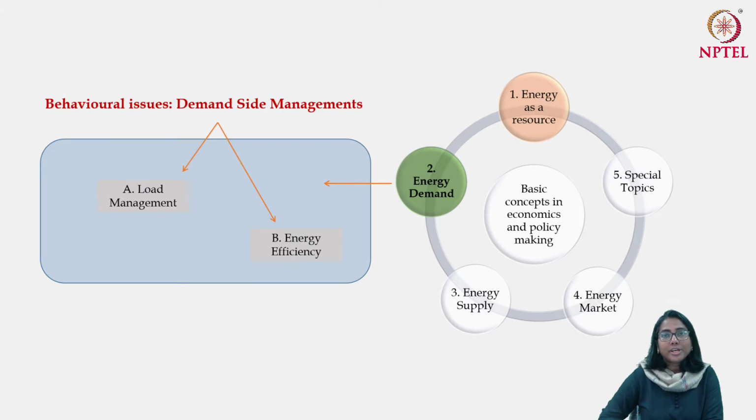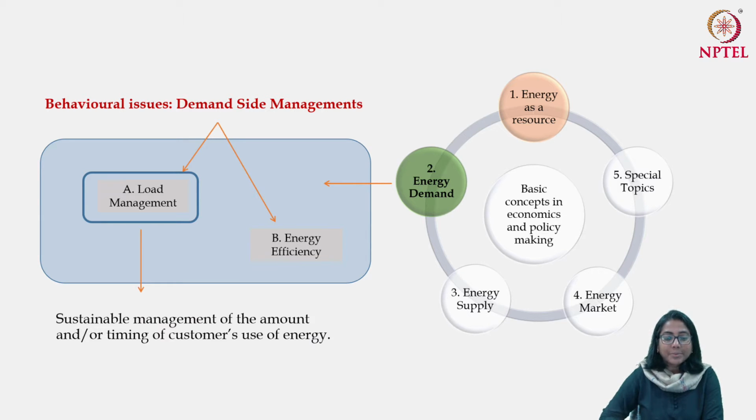Today we are going to discuss one of the very important components of demand side management, which is called load management. As you know, we are discussing energy demand under module 2, and today we are going to discuss load management. Let us start with the concept of load management. What do we understand by load management? This is basically a sustainable management of the amount and/or the timing of customers' use of energy, and this is specifically used in the context of electricity consumption.